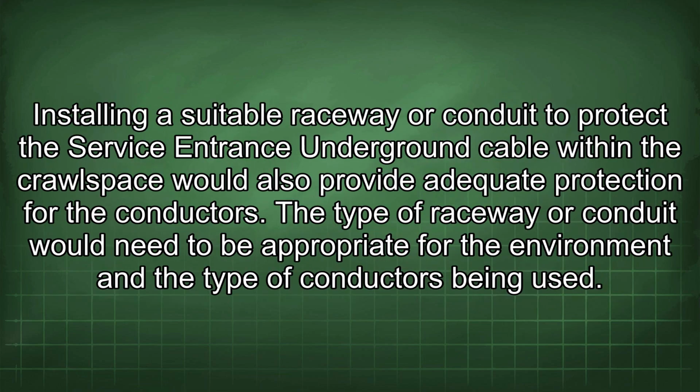Installing a suitable raceway or conduit to protect the service entrance underground cable within the crawlspace would also provide adequate protection for the conductors. The type of raceway or conduit would need to be appropriate for the environment and the type of conductors being used.